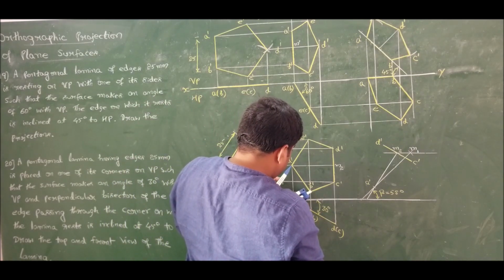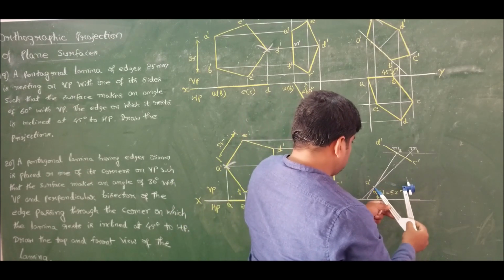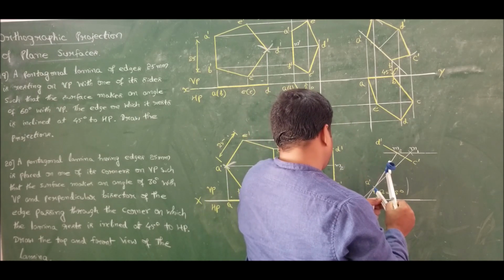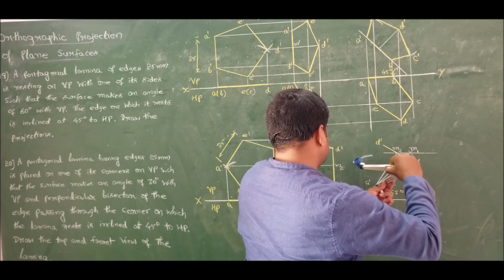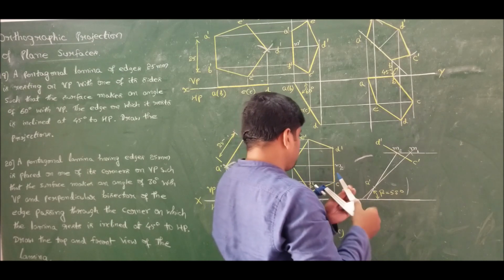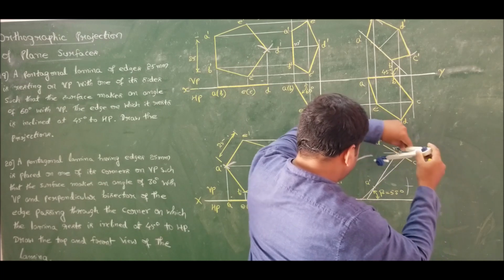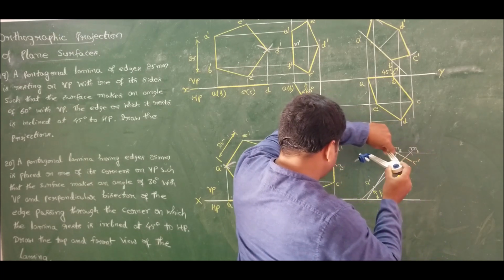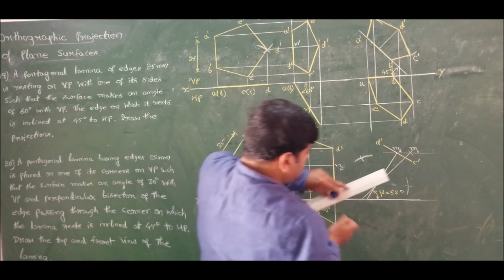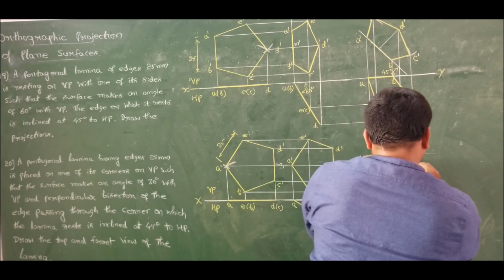Now use compass to find B' and E'. From A', measure A'B' and cut an arc. So from A' you cut another arc for E'. Now from C' you measure B'. Similarly from D' you measure E'. Done. Now connect these points to complete the problem.